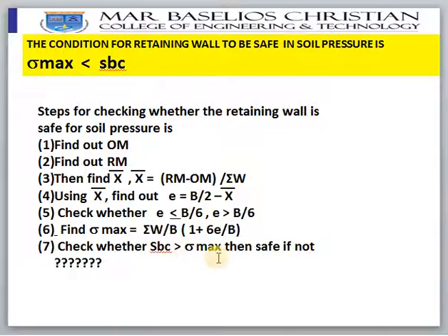Then you are safe. If it is not safe, what can you do? You increase the width of the base, so your eccentricity will be within the limit. Okay, that is what we can do.